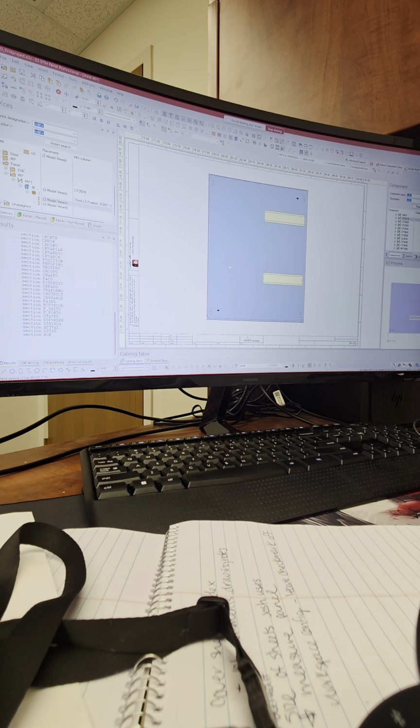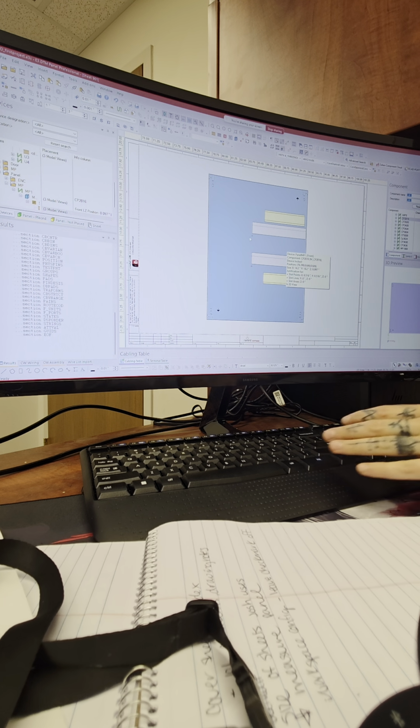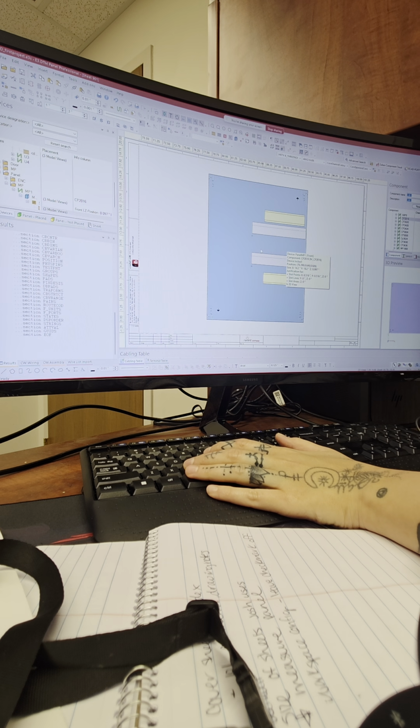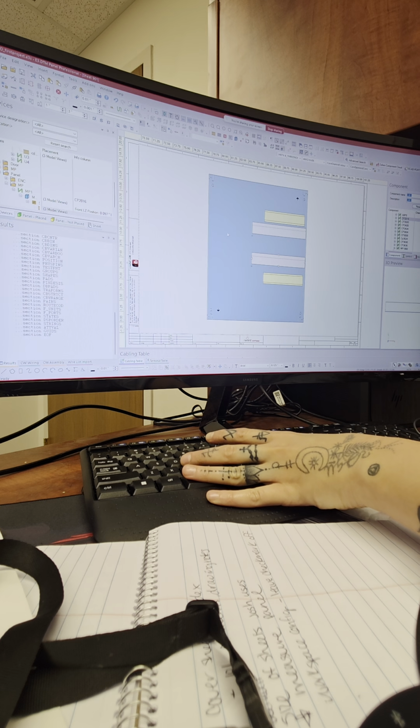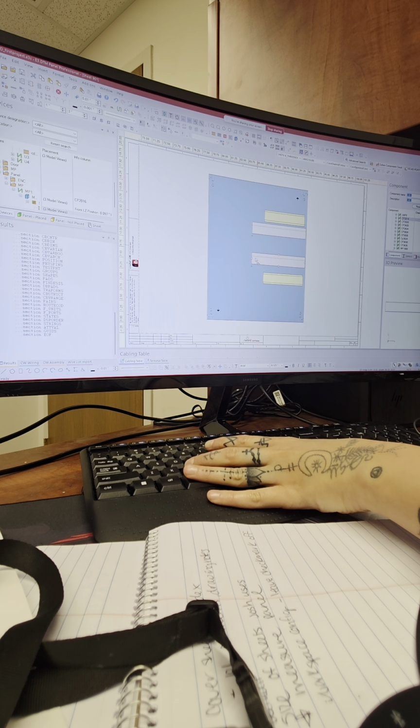Let's just say somewhere above or below these existing ducts or the existing rails. And you probably can also use a couple of these. So let's just do copy paste. You can do copy paste of these existing ones. Yeah, Control C, Control V will work as well. And then you can paste one more and then rotate it before you place it. So you can do Control V to paste, but then before you commit to place, you can press R to rotate. So copy it, Control V to paste.